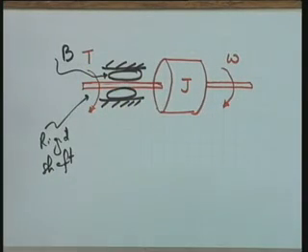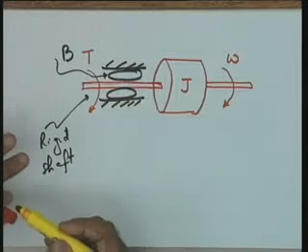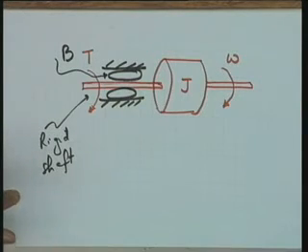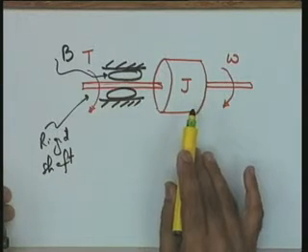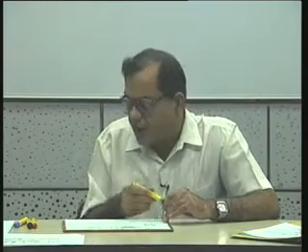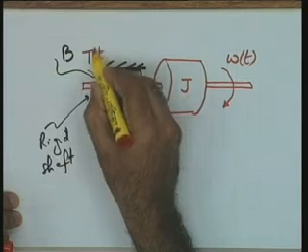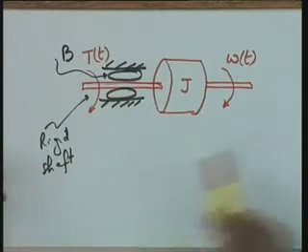This is the system environment, and as you will see, this can be appropriately modeled by a first order transfer function model. I hope the situation is very clear. The two parameters of the system are J and B. The input variable is T, the torque applied, and the output variable of interest to me is omega, the speed. omega(t) and T(t) are functions of time.